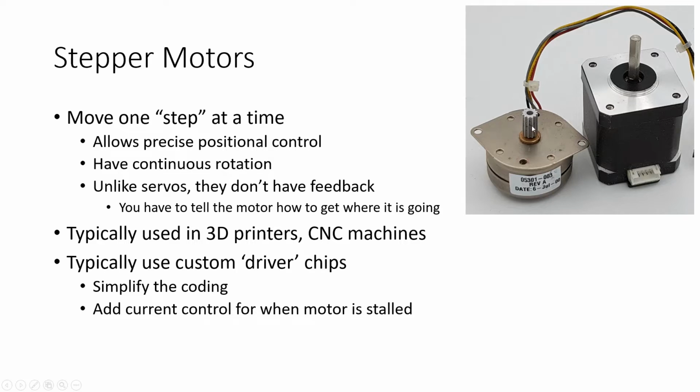Stepper motors are kind of neat, because if you grab them and twist the shaft, you can feel the individual steps as it goes tick, tick, ticking around. Typically a stepper motor will have somewhere around 200 steps all the way around. You can amplify that by doing something called microstepping, where you stop partway in between each step. What that allows you to do is spin that output shaft to the exact position that you want and hold it right there.